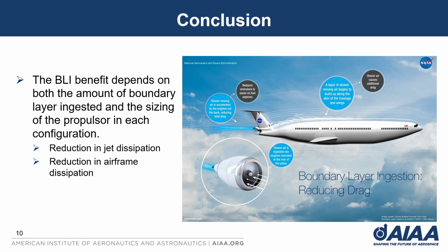And finally, the conclusions. The aerodynamic benefit of BLI is defined as a reduction in mechanical flow power required, and it was quantified with the use of a direct comparison of non-BLI and BLI propulsion installation on the D8 aircraft operating at the same condition. This benefit is mainly due to reduced jet dissipation, which generates a higher propulsion efficiency, a significant fuel burn benefit. Configurations with higher ingestion will have correspondingly more considerable benefits.